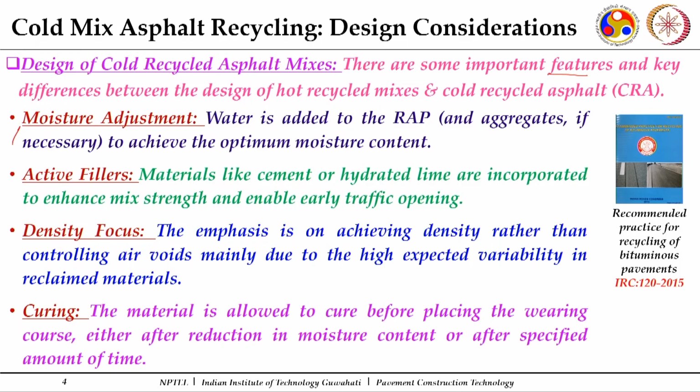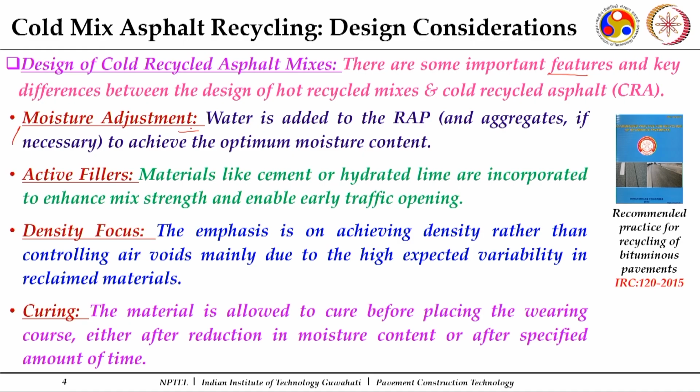As in the case of hot mixes or hot recycled mixes, we don't want to have moisture content, specifically as low as in the case of RAP. But in the case of cold recycled mixes, there is a requirement of a particular amount of moisture content, and that's why water is added to the reclaimed asphalt pavement, and added virgin aggregates may also be there if necessary to achieve a desired gradation, to achieve the optimum moisture content which gives you the desired amount of workability to get a density.